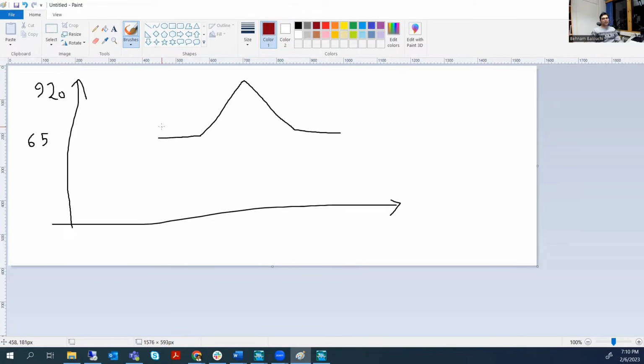So the 10 values that we use is a hydraulic warm-up. Usually, if we want to avoid shock to our model, it is better not to start modeling from this high value of discharge.